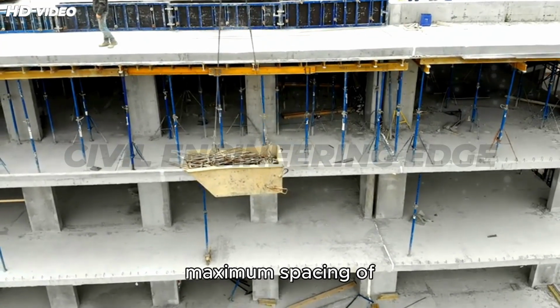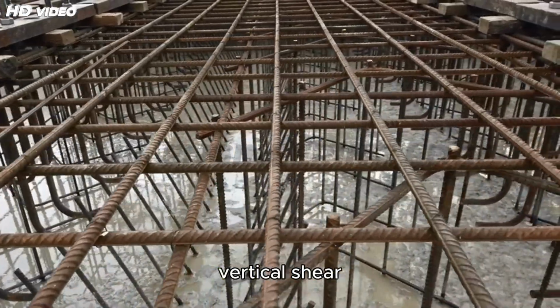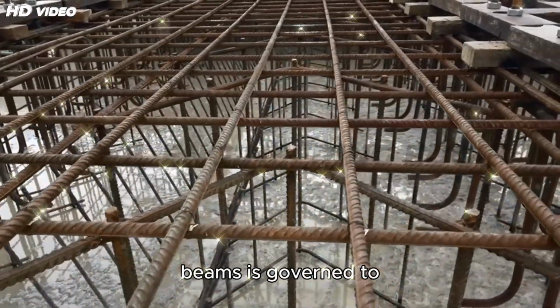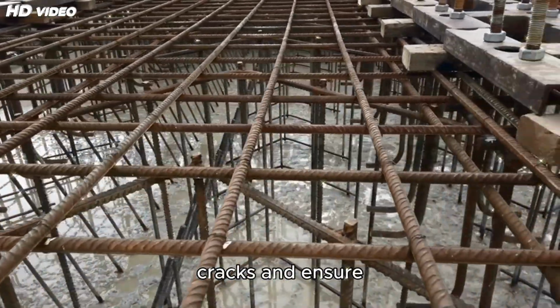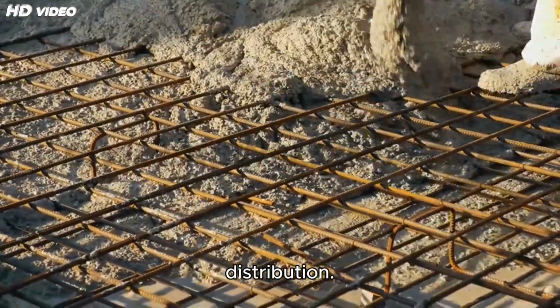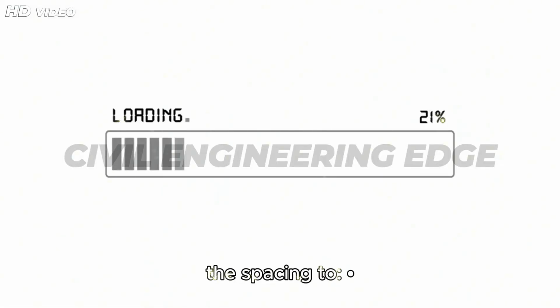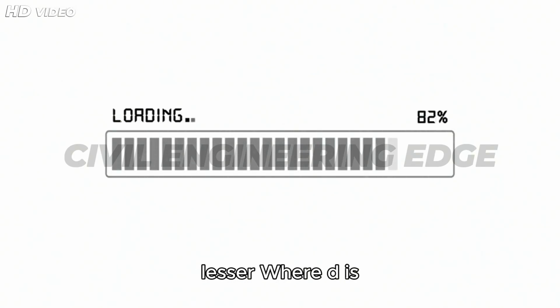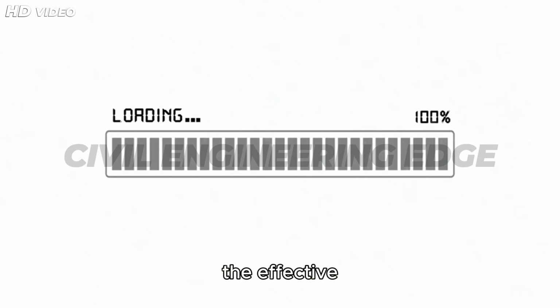Maximum spacing of shear reinforcement, according to IS 456:2000, Clause 26.5.1.5. The maximum spacing of vertical shear reinforcement stirrups in RCC beams is governed to prevent large shear cracks and ensure uniform stress distribution. The code limits the spacing to 0.75d or 300 millimeters, whichever is lesser, where d is the effective depth of the beam.